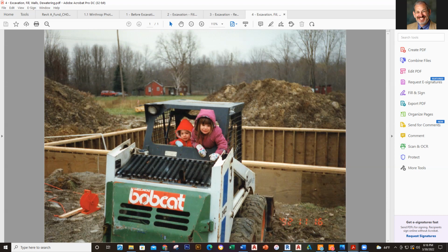Now, this is November the 16th, 1992. So we're only 5 days past the last one. You're going to notice there are walls in the hole, and they are the type of which I spoke, your pressure treated lumber, which is waterproof and keeps the water out. You're going to notice something else over here: you're going to see this white tube right here.